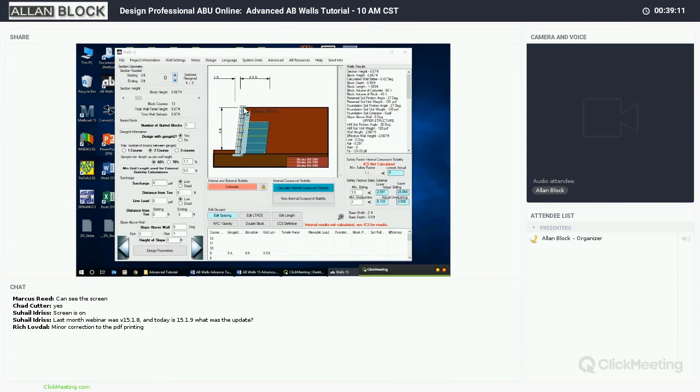So instead of a double wall feature, what you can also do is what we call the no fines concrete. And so I'm going to unlock this, calculate it so it goes back to standard, because this is one way to get back to just as if you calculate a section for the first time. I go to a no fines concrete gravity wall, and I click on the course, and it tells me, do I want no fines concrete on top or bottom? I'm going to go top, and let's try that 2-foot mass.